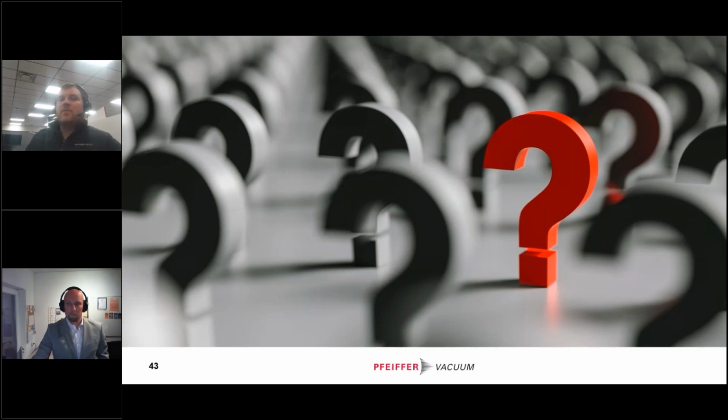But really what it's going to come down to is you have to look at your volume and calculate how long it would take to evacuate that volume down to something like 10 millibar or less. And then from there, give yourself a couple seconds to take an actual measurement and either look for flow or pressure change. And that'll give you a minimum amount of time that you're going to need to perform a go/no-go test.